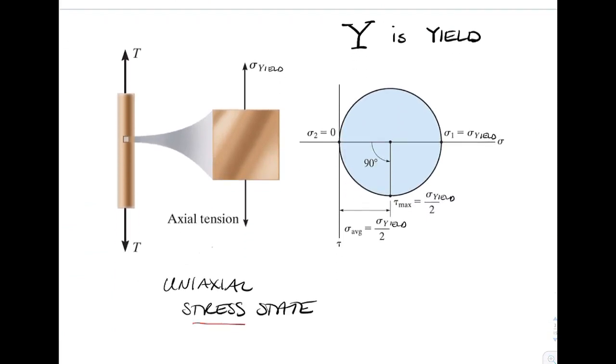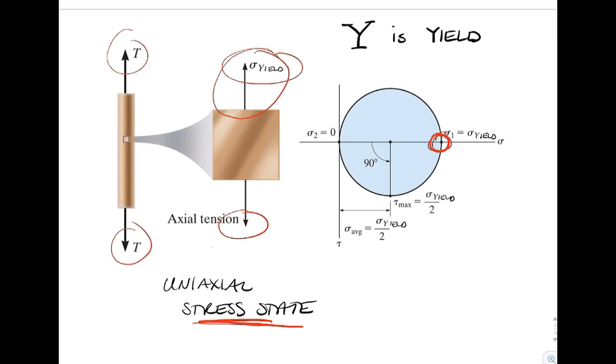So we'll explore a ductile material. Here would be a specimen in a uniaxial state of stress, where stress is applied along one axis only. If we draw a circle, we can plot the stress on this face at that point. The other two faces would have zero stress, and we'd have a plane stress condition, a free surface. So if the stress is equal to the yield stress, you'll see that as a capital Y or just sigma with subscript yield.